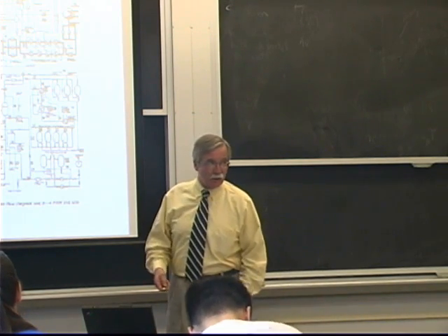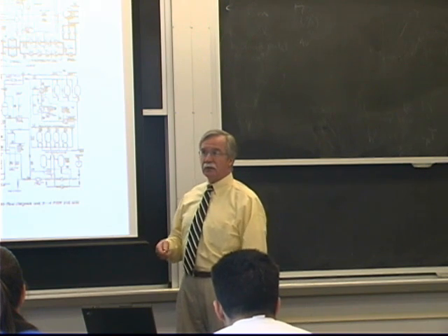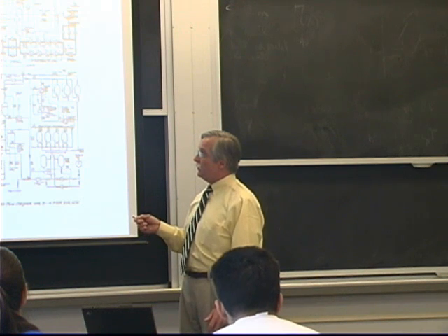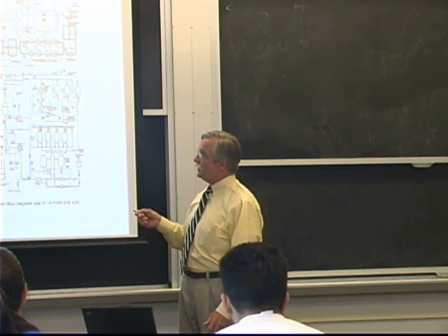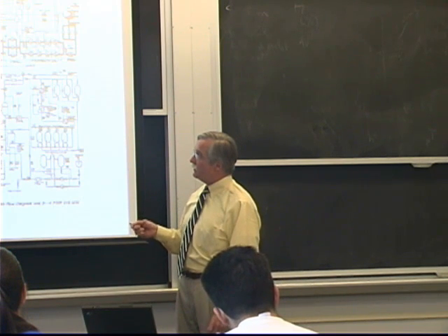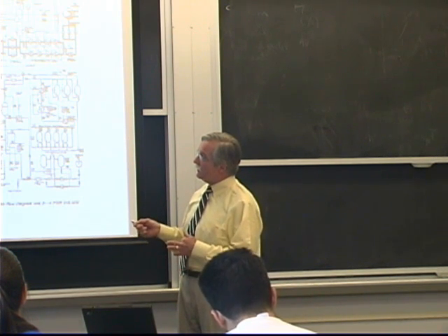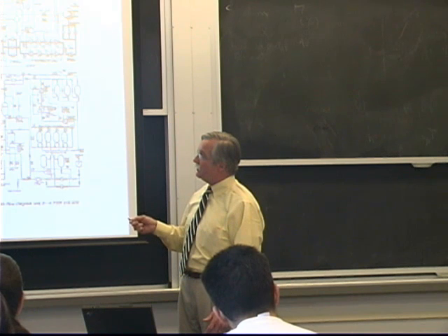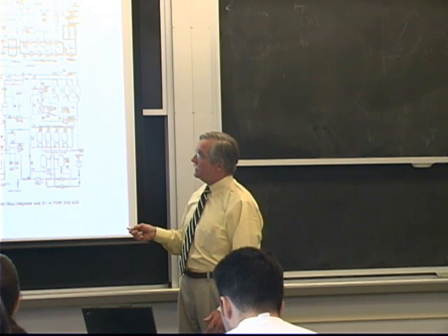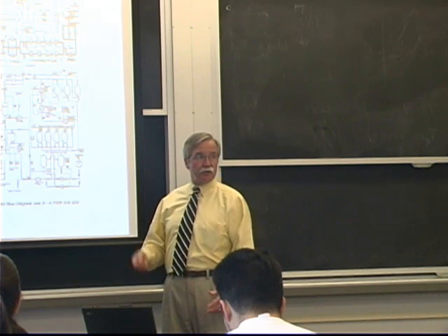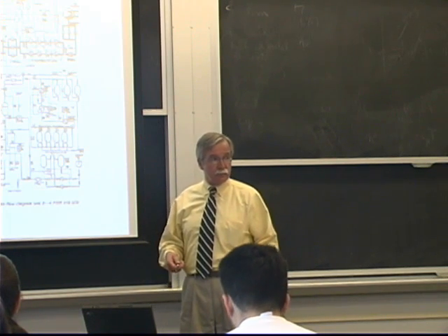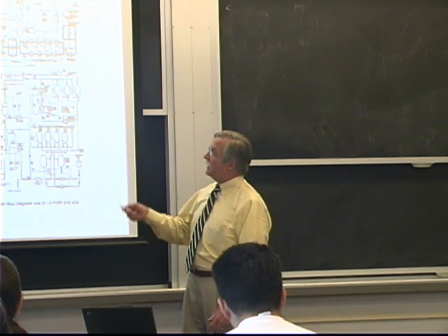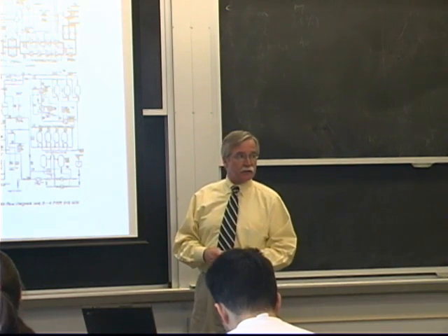On the ESBWR, they decided to make a natural circulation reactor, where you make a very, very tall reactor with a chimney. We haven't talked about BWRs yet, but prior to doing that, I'll give you a brief introduction to how a boiling water reactor works with internal recirculation pumps. They got rid of those, and they're using natural circulation to cool the core. Again, more passive, but they still have feed water pumps. That would be a good exercise with the Part 52 process. We'll see if we can work that in.